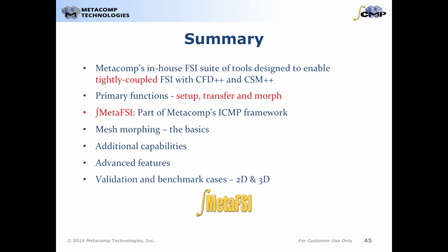To summarize, MetaFSI is Metacomp's in-house FSI suite of tools that are designed to enable tightly coupled fluid structure interaction modeling by working seamlessly with CFD++ and CSM++ or other third-party structural solvers. The primary functions of MetaFSI are to set up and test the mesh morphing, transfer loads and displacements between CFD++ and CSM++, and more importantly, to morph the CFD++ domain based on the computed CSM displacements.